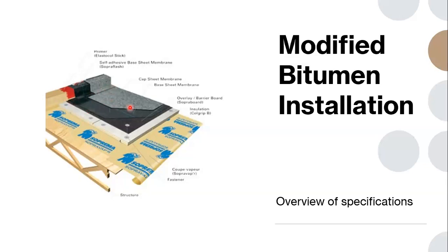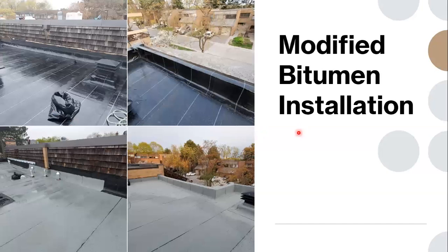Another important thing to consider with this type of membrane installation is that the stripping and the field membrane seams from the end of the membrane shouldn't be in line. There should be a stagger between them so that if water is coming in, it's not going to travel down the membrane, hypothetically. So just looking at that with an actual membrane installation, again, you can see both with the base sheet and the cap sheet along the field and the stripping, you have staggered. It's a continuous run of membrane, not cut into several pieces and just puzzled all over the place.